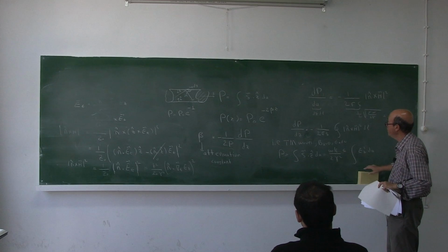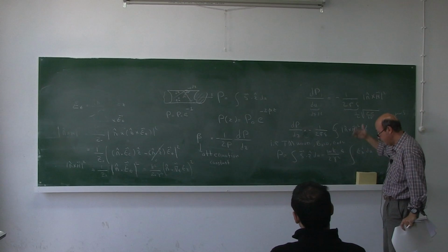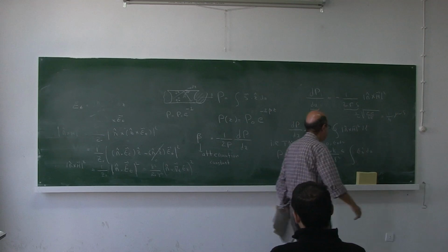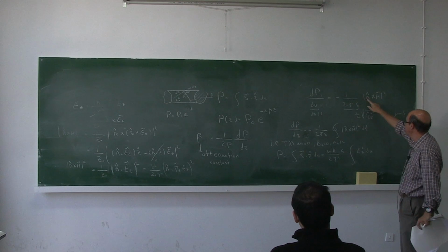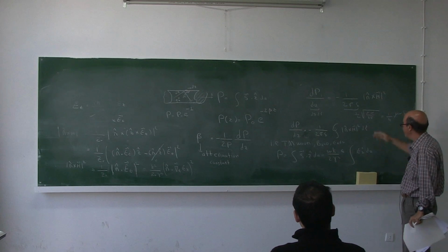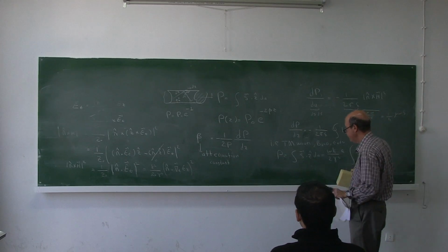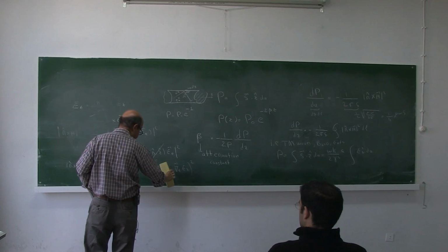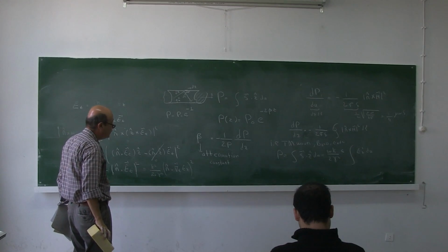And then we go to what we know for the power loss per area for electromagnetic waves which reflect from the walls of the conductor. We know that the power loss is related to the skin depth times n cross H. N cross H is nothing but the surface current density, and we calculate the n cross H for the TM waves. We end up that n cross H is related to the n dot gradient of the z component of the field.